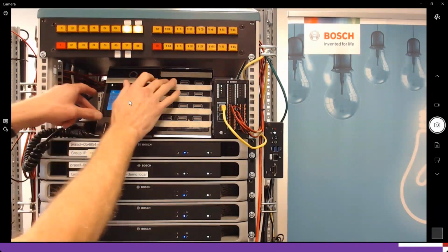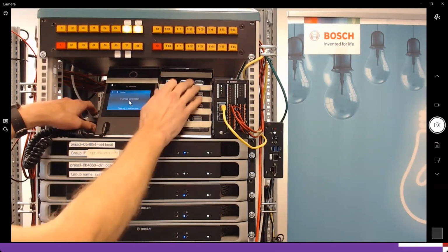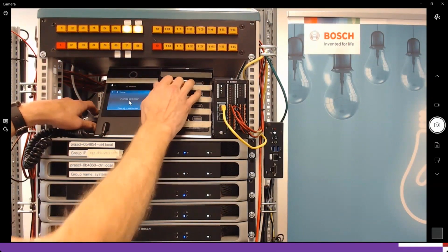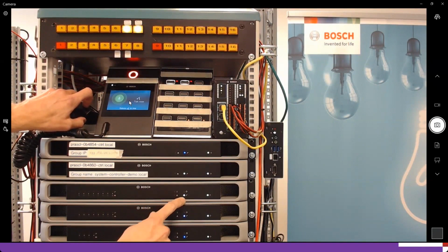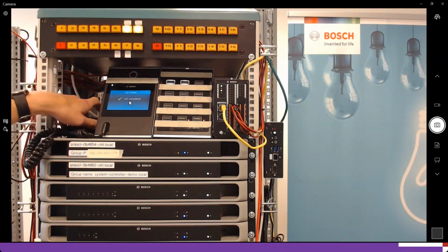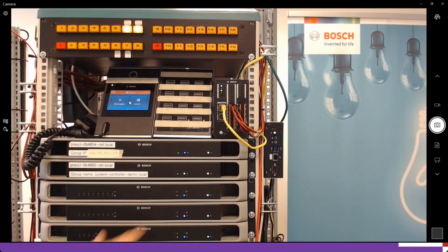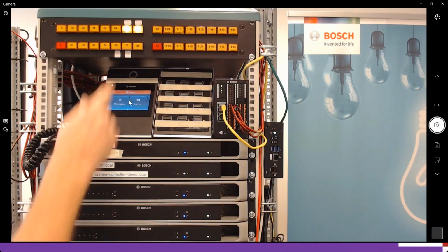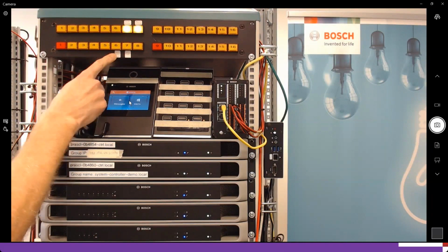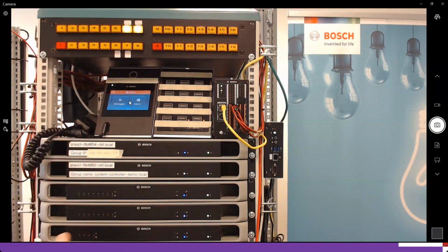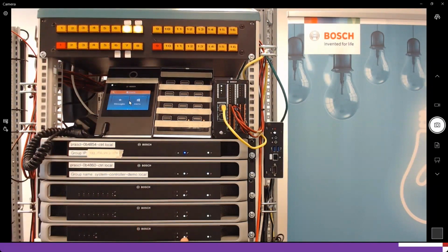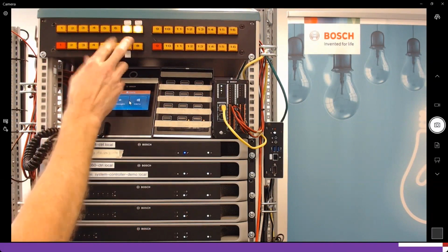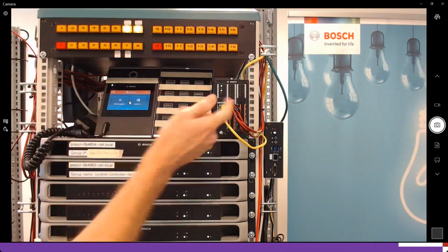If you want to make a call still for the emergency, maybe for 2 zones, now you see the amplifier where the zones are going to is active again, and the others stay in their snooze mode. And then I stop the call, and now you see it's getting back into the snooze. Until the external mains fault is recovered, or that you regularly have to do some checks on the loudspeaker lines, and then when it's recovered again, you see now everything gets green again and it's active. So this kind of control you could also deploy on the IO module.